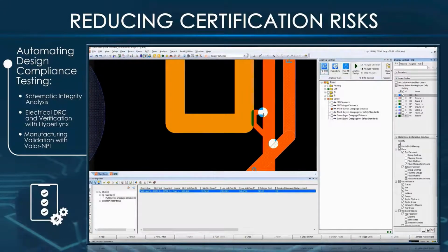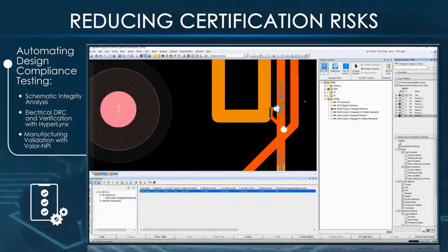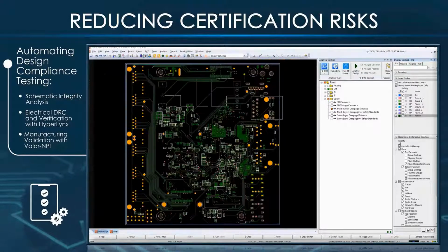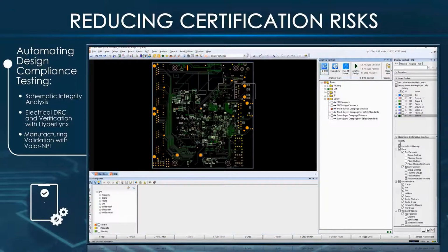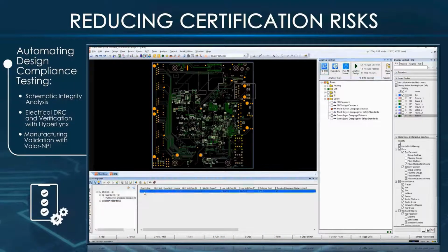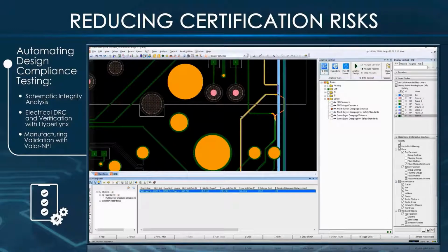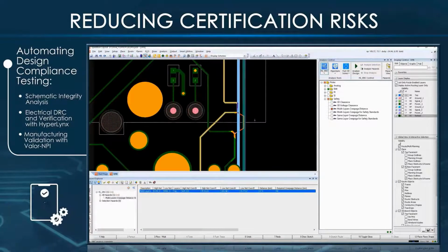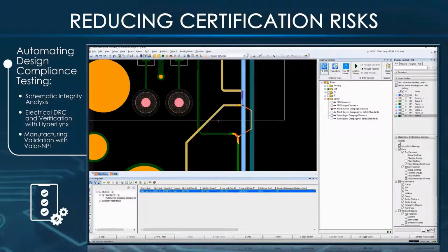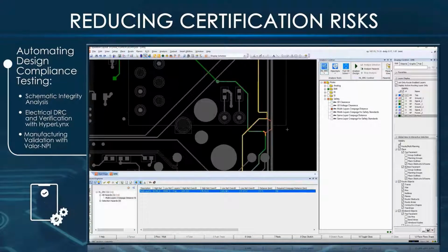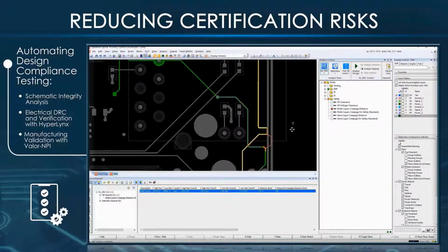In this case, we have a high voltage 100 volt net aggressor on the top side of the board. You can see it's going through that slot in the board to the bottom side and affecting an object on the bottom. It's very tedious to check creepage for high voltage this way. Another example is the board edge. We have that khaki 100-volt trace on the top side of the board, and we can see that it's creeping around the edge of the board and affecting a net on the bottom side.